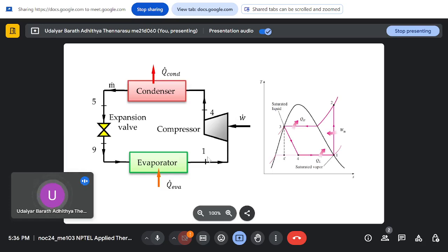So with that, next we saw was vapor compression cycles. A vapor compression cycle is similar to a Rankine cycle, but you are running it in reverse, and instead of isentropic expansion, you use an isenthalpic expansion. So it's simpler, because you cannot handle two phase.